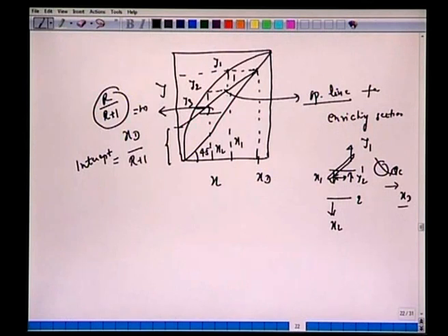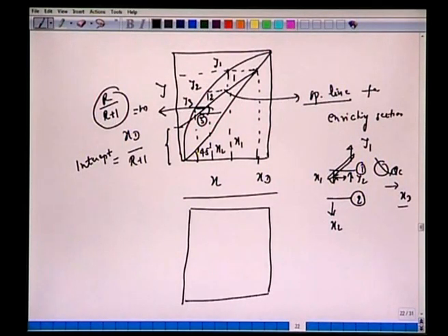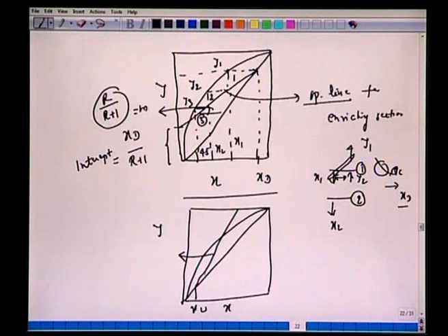The first stage is 1, the second stage is 2, this is stage 1, this is stage 2, and so forth. We have stage 3, etc. Alright, this kind of construction can also be done for the bottom section. If we have x and y here like this, we start from xW, and with the equation of the operating line, one can also obtain this. We can also have the number of stages here; this is the stripping section.